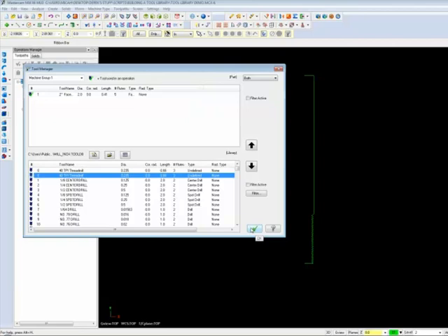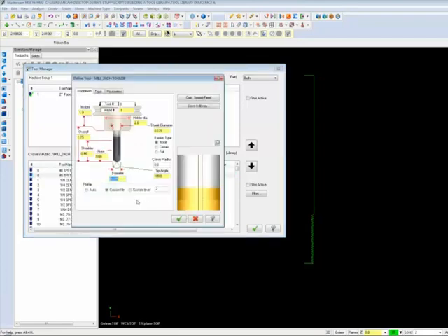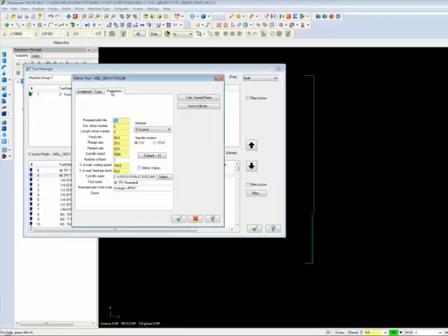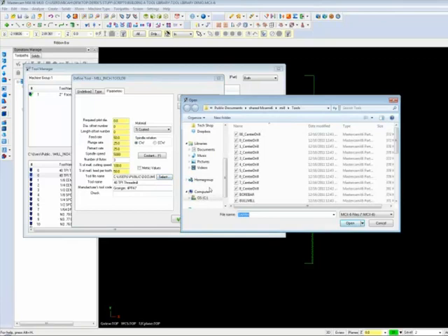Did he pick a file and define that file? Let's go back real quickly. Go back to the picture. Sorry, let's do one thing. Go to the last page. Down there where it says select, right there, select, and make sure you selected that profile. See, in this case, you got a tap right hand. I should have also pointed out, when you first set it up, it's going to prompt you. Now that you went back in, you needed to go back in here and define that tool.